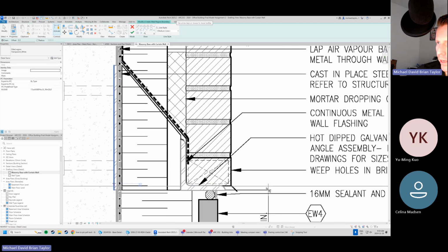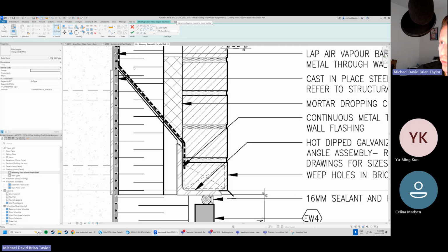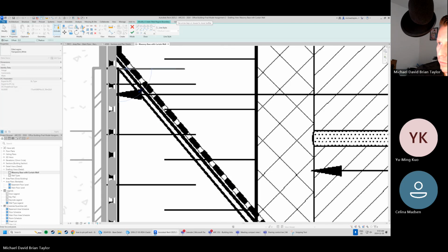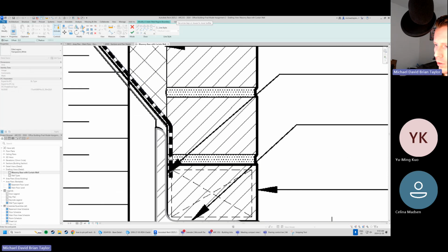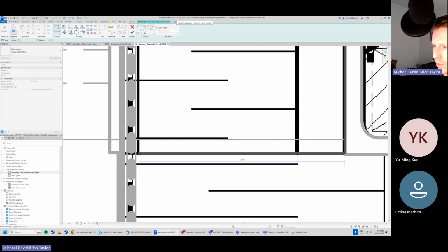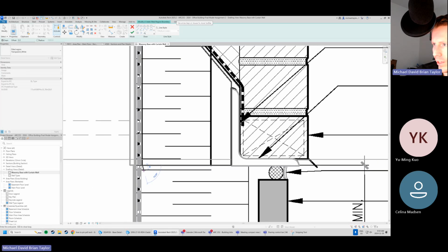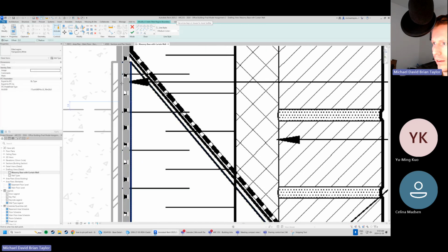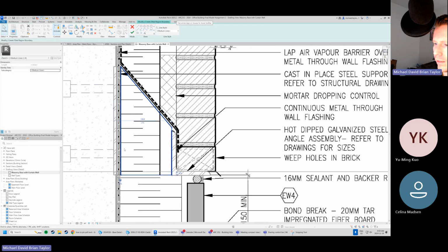So we've drawn our plate, and now we're going to draw our little piece here. So remember closed loops. So I'm just going to quickly do this. Try and keep your numbers roughly accurate. So I can see here I've got a closed loop. I'm going to hit check mark.